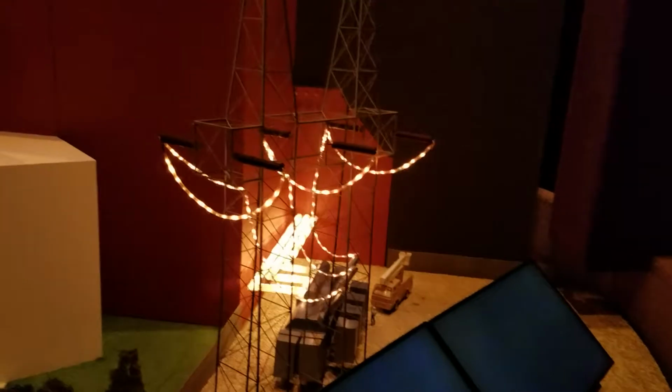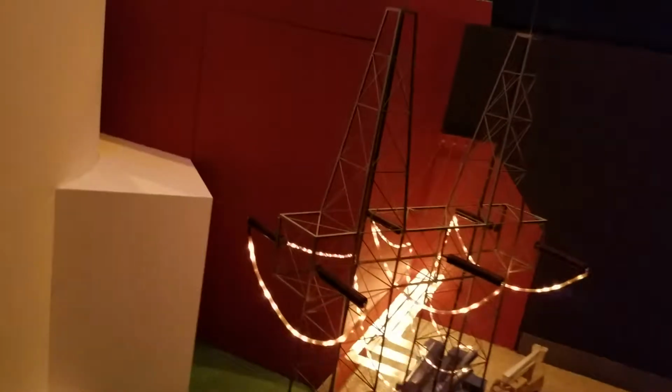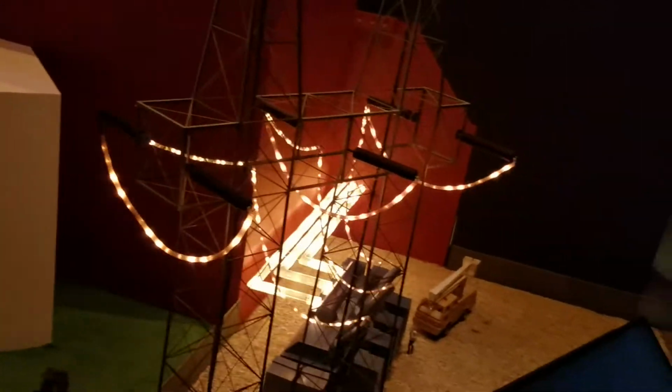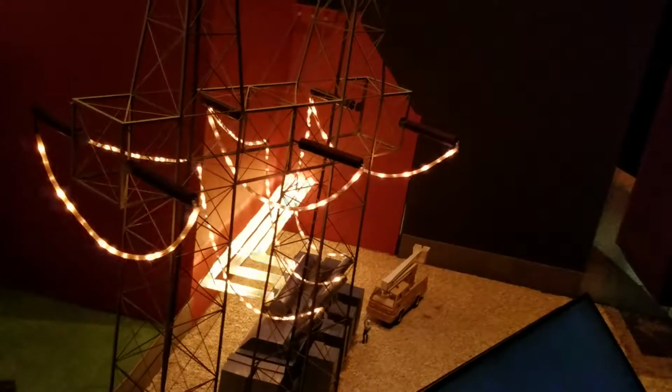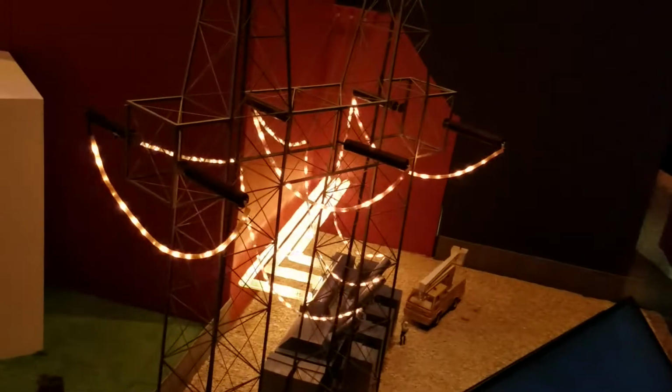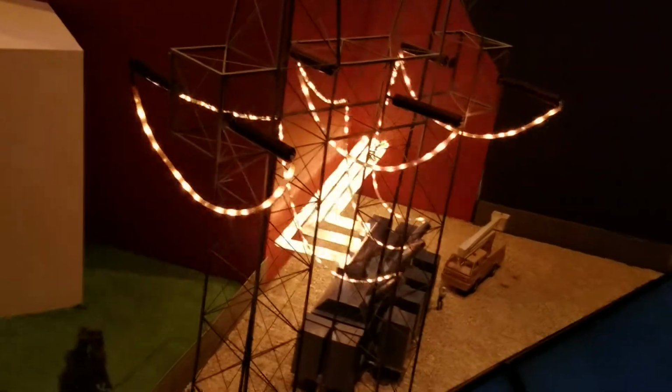This transformer steps up the voltage to the higher level needed to transport the power efficiently to the points of use, which can be hundreds of miles away. The higher the voltage, the greater the carrying power of the transmission line. Cook plant transformers boost generating voltage from 26,000 to 345,000 volts on Unit 1 and 765,000 volts on Unit 2. Let's see how power gets to your home.